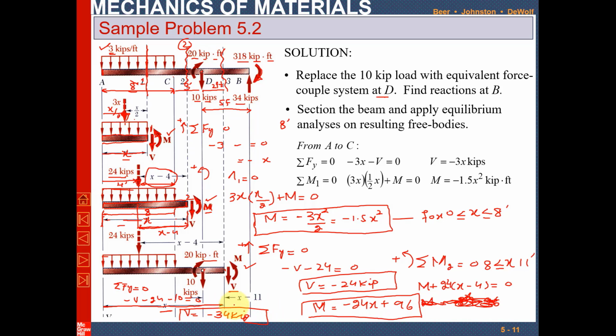And you can also find the bending moment equation at this section by using the equation that the sum of all moments about point 3 is equal to 0, and it will yield an equation for the bending moment through this region.